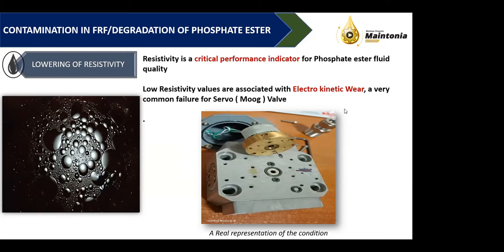But during the startup of the unit, rich fuel is supplied to the furnace, and the furnace is not exactly designed for long operation on that rich fuel. So unburned gases come out, and those are not like the gases coming out during regular operation. So a startup is very, very dangerous compared to normal operation.